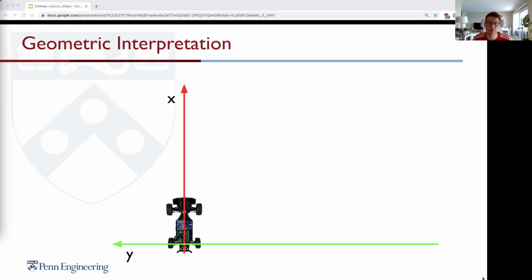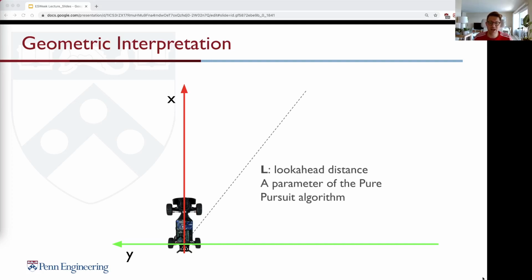We now introduce the concept of the so-called look ahead distance with the parameter L. What we are doing is searching for a waypoint that is close to this predefined parameter we call look ahead distance. That means we now look one distance ahead, for example 1 meter, and we are searching now for a goal point x and y. This x and y point needs to be on the race line or is referenced on the race line because that is what we want to follow.